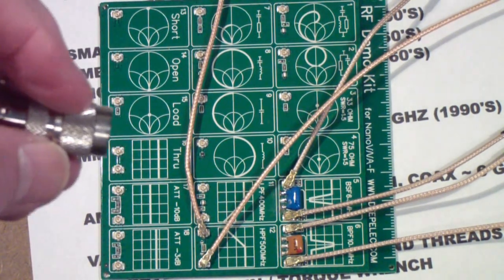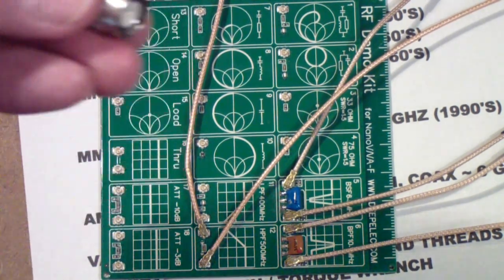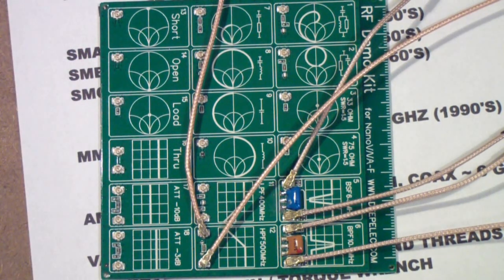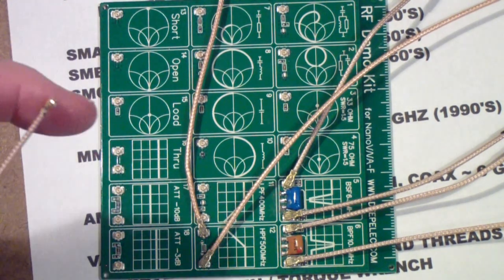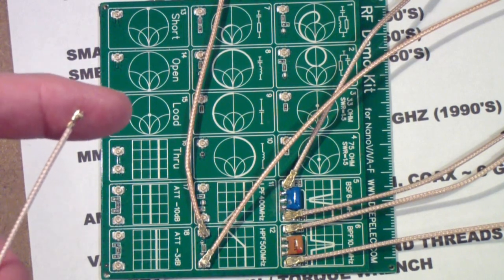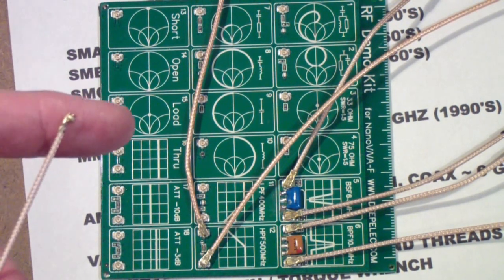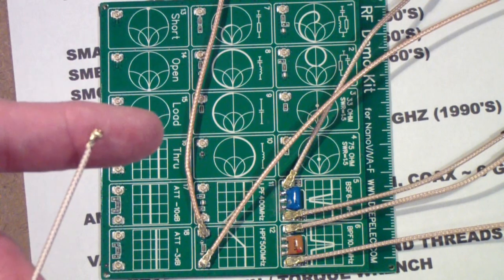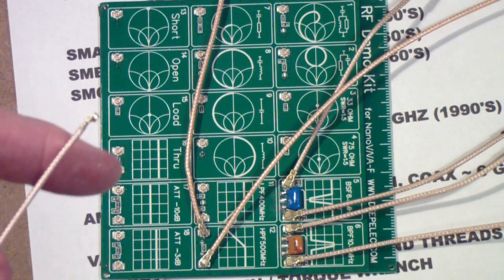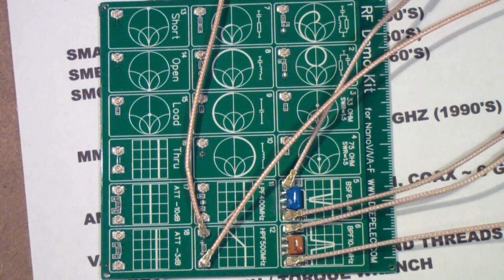These are made, the latter connectors are made to be connected and reconnected many times, usually hundreds of times, and they usually will last thousands of mating connections. But these little micro coaxial connectors are only intended to be mated 30 times. That's their rating. Now, some of them will last longer than that, but it's not something you're supposed to plug and unplug very much. It's supposed to be, you assemble the unit, you put in the cables, you connect them, and you leave it alone.